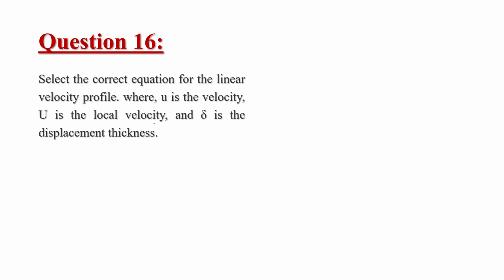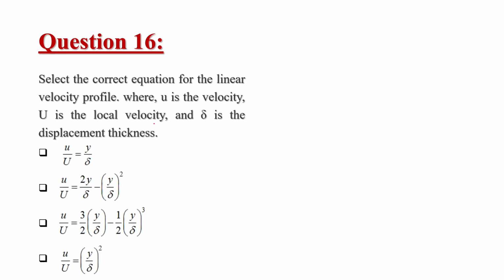Here you can see that from here to here we have a high change in velocity because all the layers are parallel to each other. But here, because of this mixing effect, the velocities are almost similar. Because of this we will be having an almost flat velocity profile as we move to a higher Reynolds number. If we move further higher, and this will happen if we go on increasing the Reynolds number, the velocity profile tries to be flatter.